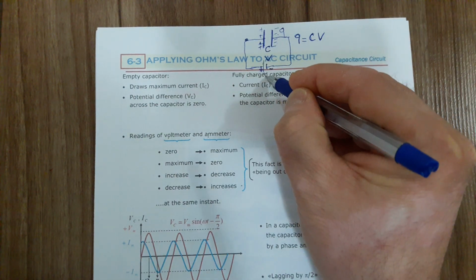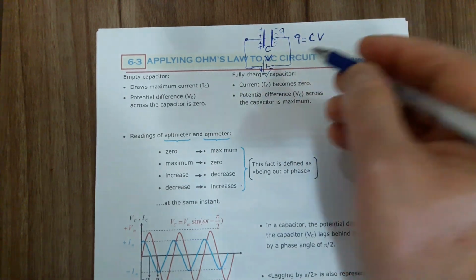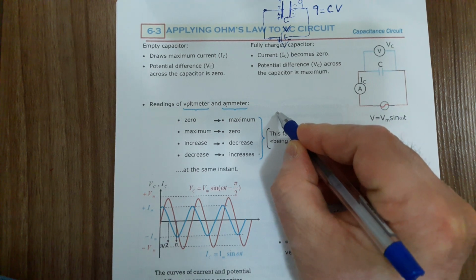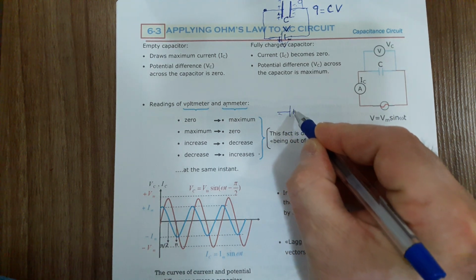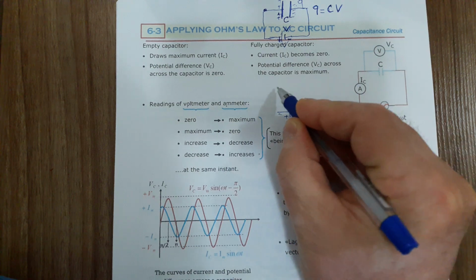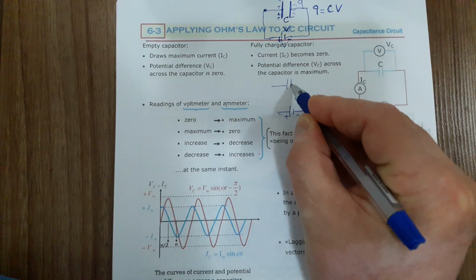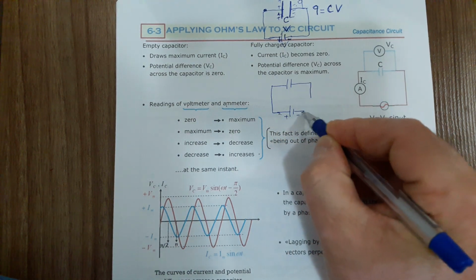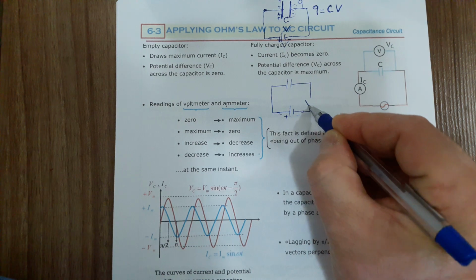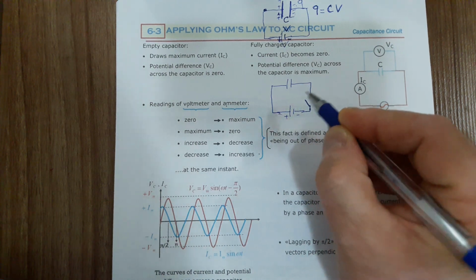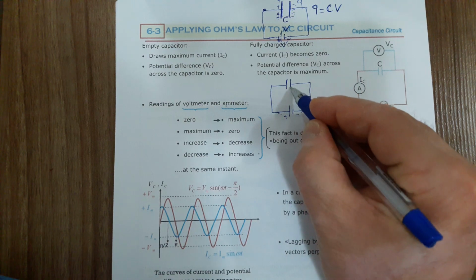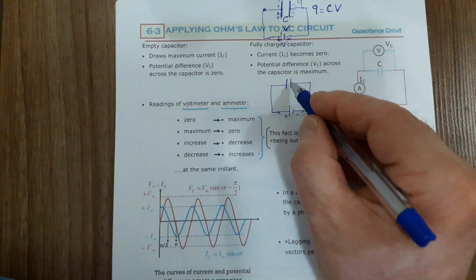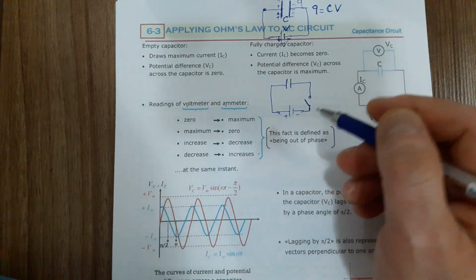But when you attach a capacitor to a battery, let me draw here again. So this is the battery, with a negative and positive terminal. If you attach a capacitor to a battery, of course we need a switch here. Assume that the switch is initially open. When it is open, there will be no charge stored in the capacitor. There will be no polarization of the plates, so the potential difference between the plates of the capacitor will be zero.